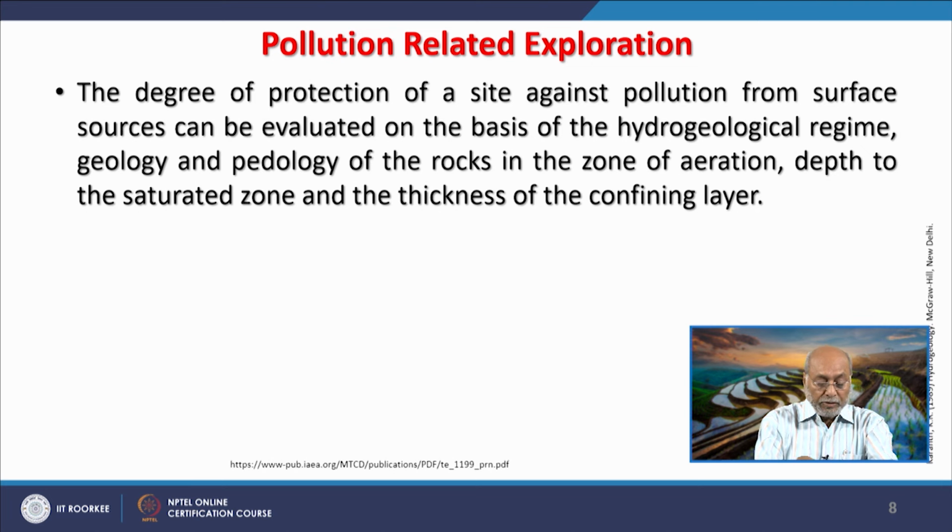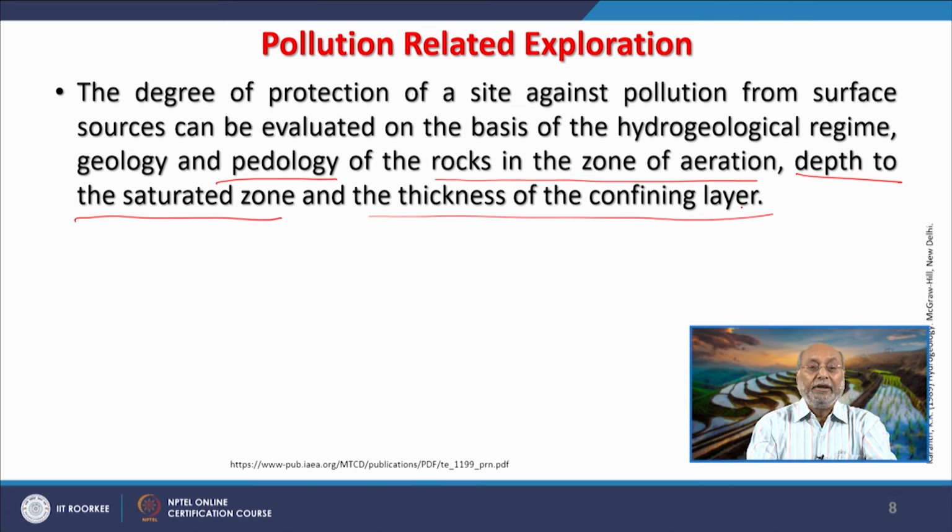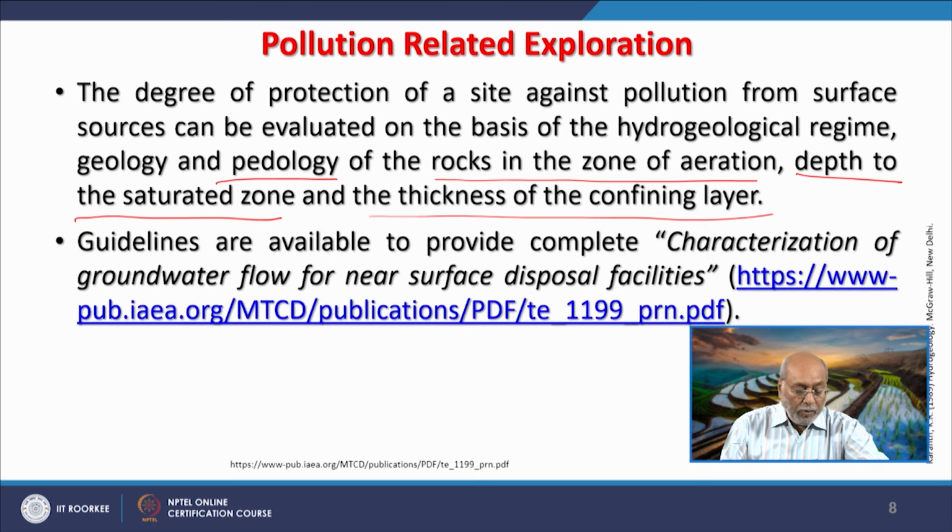And of course the pedology, meaning the soil, if there is a soil cover, that kind of information is also required. Further, we require the zone of aeration, the depth to the saturated zone, and the thickness of the confining layer. All that information will help us choose a correct site for disposal. Now, there are guidelines also available, which is a characterization of groundwater flow for near surface disposal facilities.